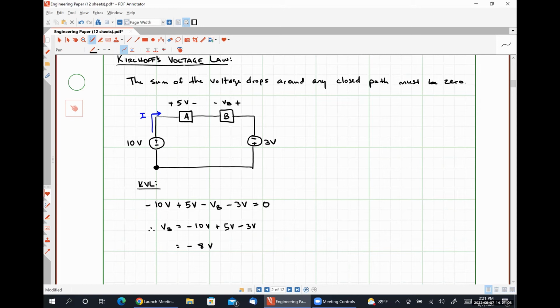All right. So one thing that I have seen students struggle with is determining a voltage like this that I'm about to show you. So what if we wanted to know this voltage drop, Vx? So one thing that students seem to find difficulty with is acknowledging that there can be effectively a voltage drop across this open circuit in the middle of this circuit.